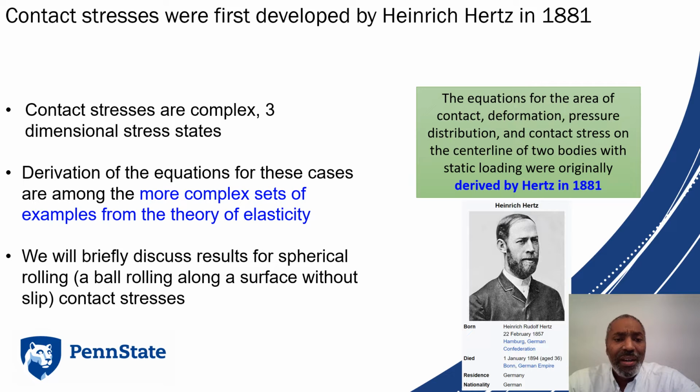Contact stresses are complex three-dimensional stress states. Their derivations come from that set of equations, which I showed you a couple of lectures ago, where we have constitutive laws, we've got equations of equilibrium, we have strain displacement relationships.